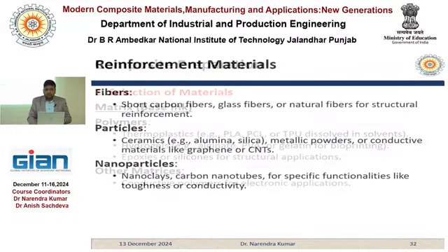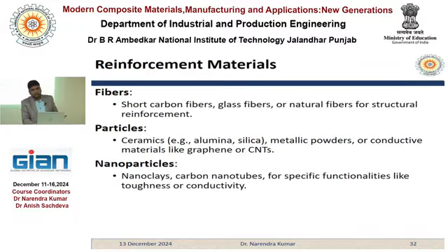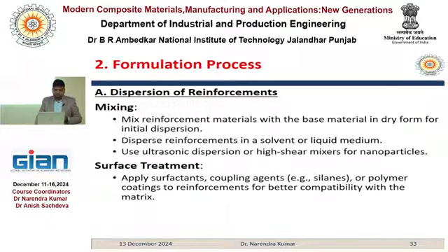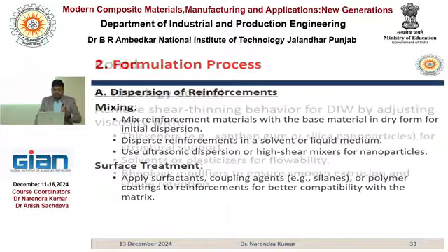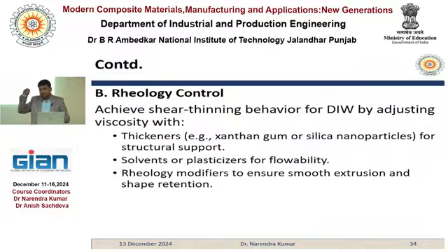Depending on your requirement you can select the matrix material and reinforcement material, and initially the same thing that we have done in the previous case, mixing, and then you can add some other agents to ensure the viscosity, because we need to extrude the material through a small nozzle, a needle basically, right? So you have to ensure the viscosity.